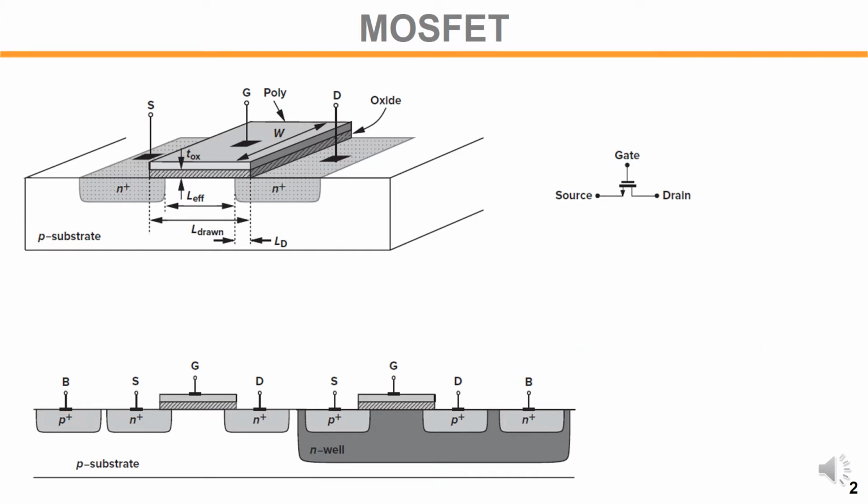Let's take a closer look at the PMOS device. So the PMOS body is tied through the N plus, and the PMOS body is N-type, the N-well. For the PMOS, we have a parasitic diode here.